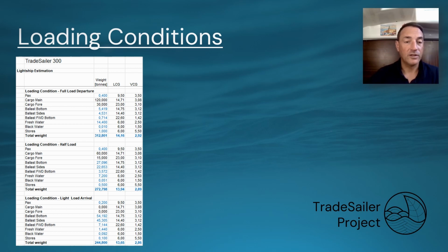All right, so as you can see, you've got the cargoes, you've got ballast water as well. So there's not much ballast water when the boat's fully loaded, and in the light loaded, when there's no cargo, there's lots of ballast water. The final amounts of ballast water I will know once I've done the stability, and we can see how much we can reduce it to still stay on a good waterline and meet the stability requirements.